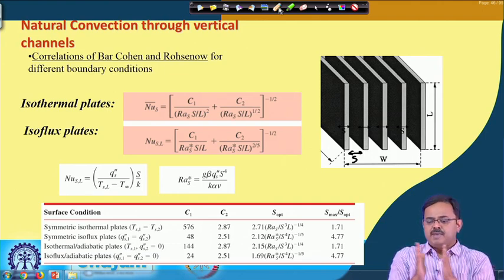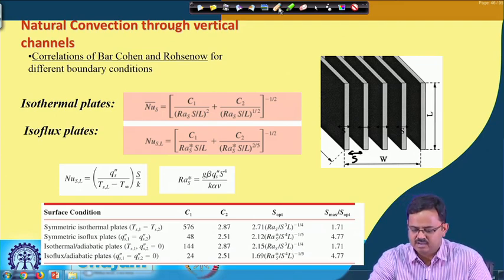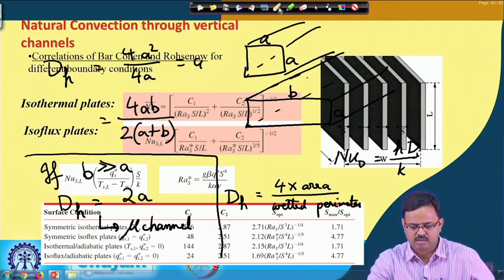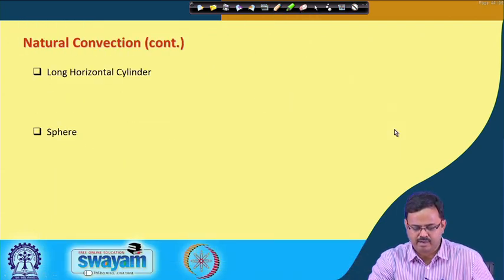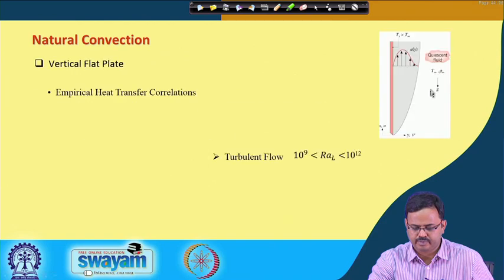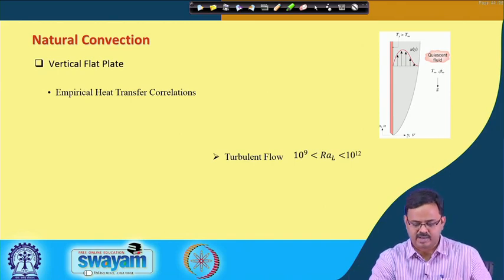Okay. So, S max is when beyond a point this plate does not even feel the presence of this plate, and that is when these boundary layers that we saw 2 slides back, there will be a boundary layer on this surface, and if you have another one next to it, there will be another boundary layer. When these boundary layers do not overlap, then that is the optimal spacing, where the heat transfer from this plate is going to be maximum,